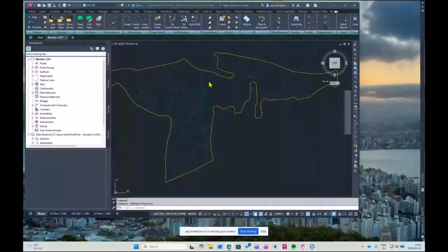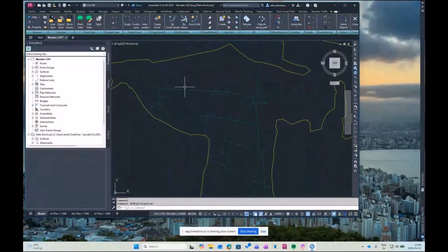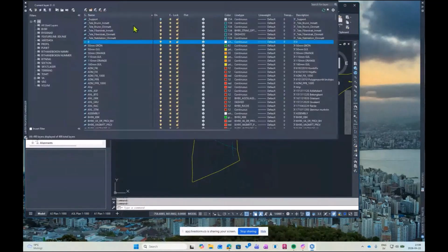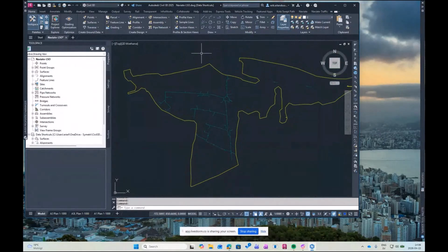The first thing I would like to do is to turn off the manholes for this area, since they are also line objects. And we do that by going to the layer properties and turning them off. The reason I do this is because line set will go on the polylines, feature lines, and lines, and I do not want to make pipes out of those.